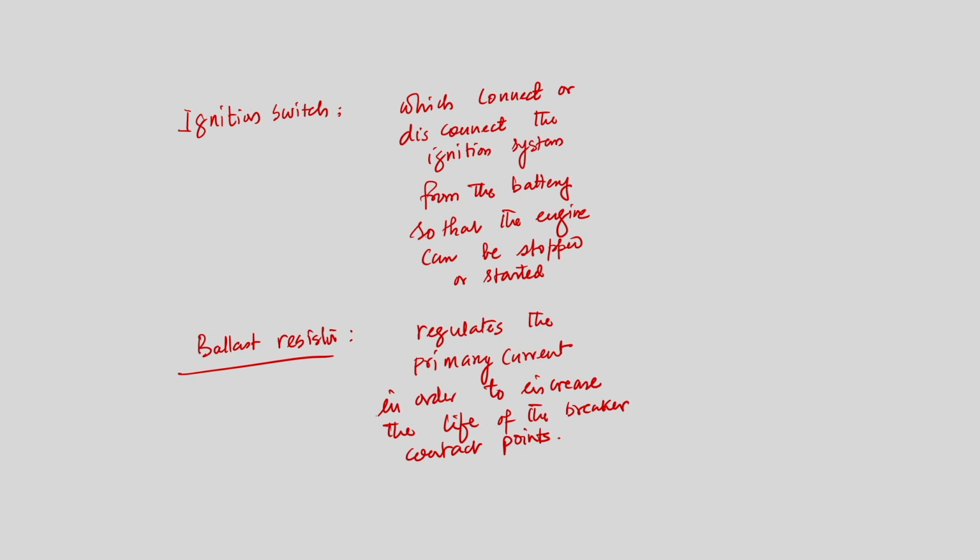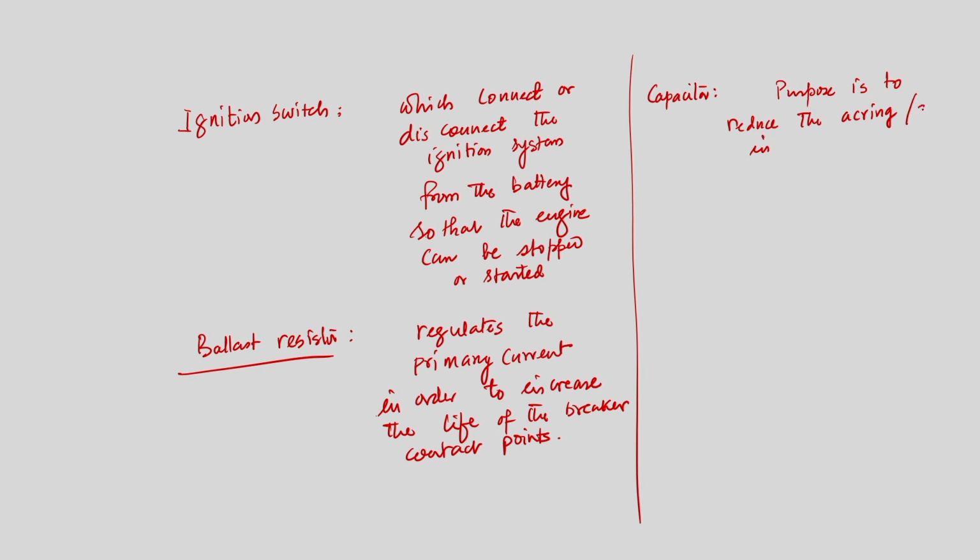Now, then of course, we have the condenser, the capacitor. Its purpose is to reduce the arcing or arcs in the breaker point, thereby increasing their life.